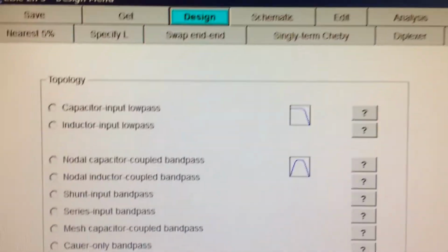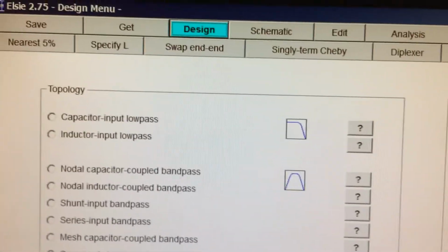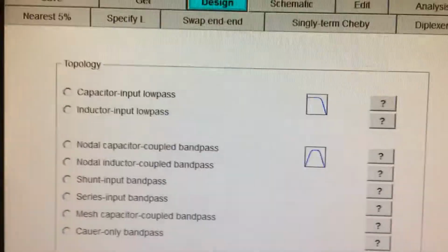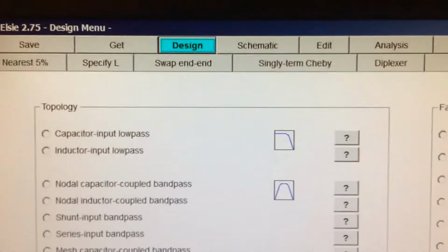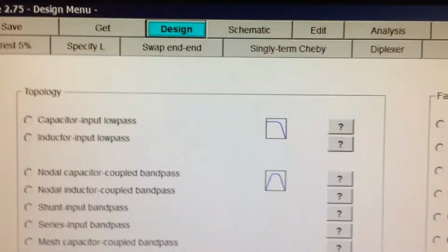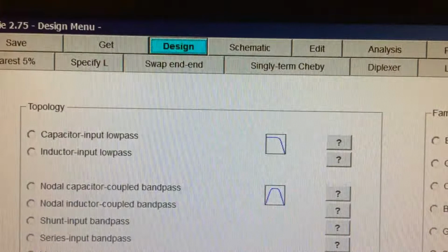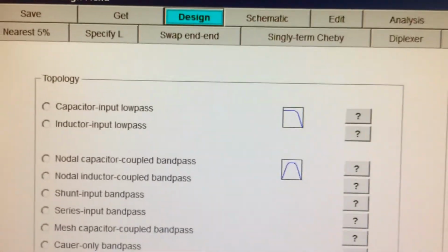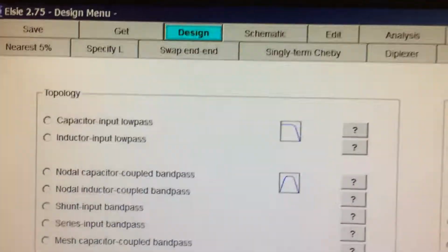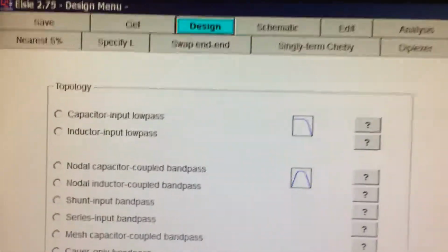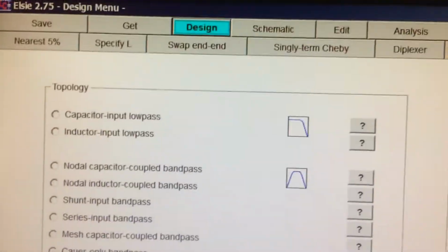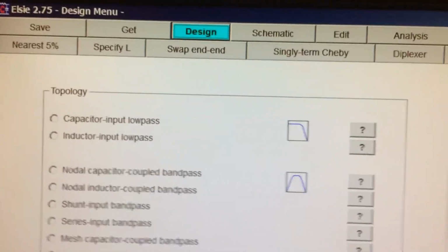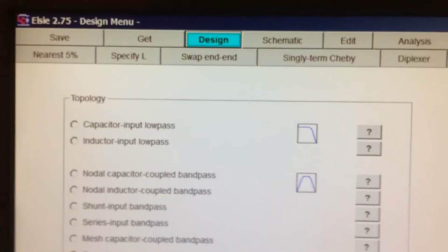So why have 5 poles and not 7 poles? Well, it depends what the roll-off is and what you really need in order to attenuate the harmonics in the bands that you're transmitting on. And typically a 5th order filter gives you a good roll-off. A 7th order filter gives you even a sharper roll-off. Okay, so we'll be able to look at that once we design this.